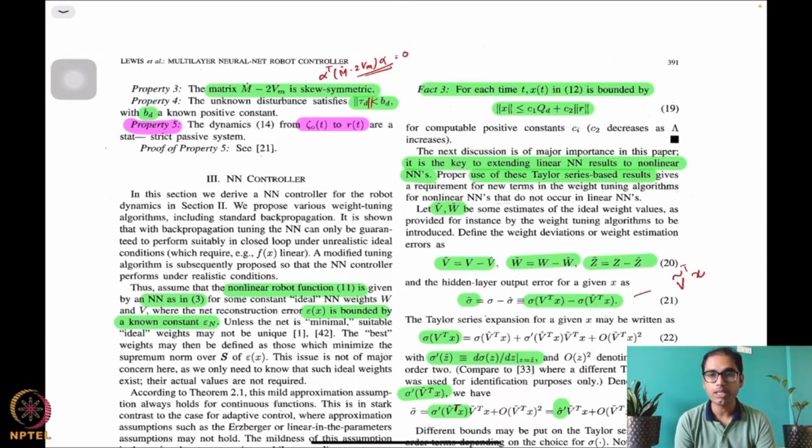A three-layer neural network being applied as a function approximator to a multi-link robot. And because it's like a neural network approximator, we don't really care to write out these mass inertia functions and the Coriolis functions by hand for every single robot. If you bring in any robot, this is like a plug and play controller.